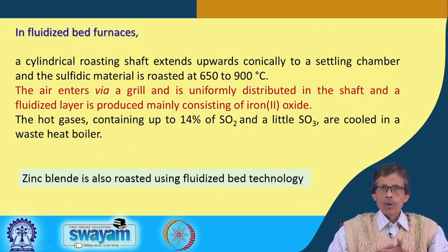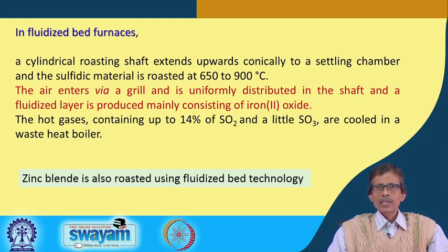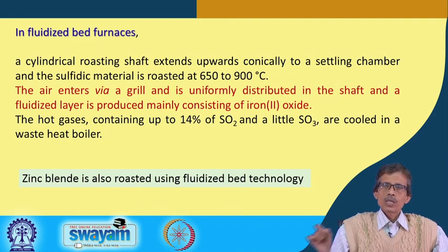So, during that oxidation process, all particles of FeS2 will be oxidized and we get that thing. That means we are only interested in getting that particular material as a gas. So, if your solid material remains intact and is only converting from FeS2 to Fe2O3, we are happy to have the corresponding oxygen for the burning process as sulfur dioxide. So, air or O2 is entering the chamber and SO2 is going out from that chamber, converting your FeS2 to Fe2O3.